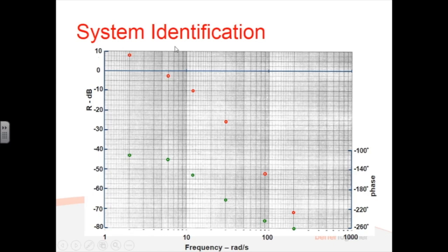What I do is start at the left-hand side and see what's going on. In this case, I'm going to start off at the leftmost point. I'm going to try putting some straight lines and see how well they fit the data. That's rubbish. Kind of okay. That's rubbish again. So I think that at least the first couple of data points is best served by that line at minus 20 decibels per decade.